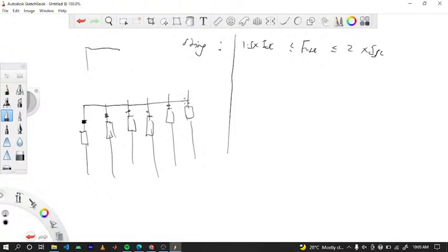Now all these currents are coming to move to this side, so you must provide protection for the entire array. So you multiply by 6, because each of the 6 strings is coming out. It will be the number of strings in parallel times 1.5 times the short circuit current. I hope it's making sense.